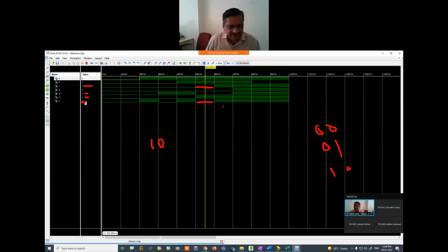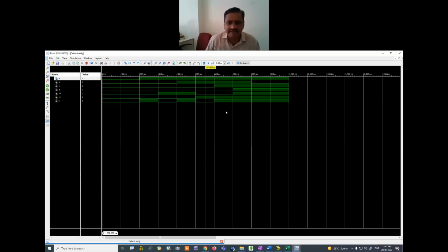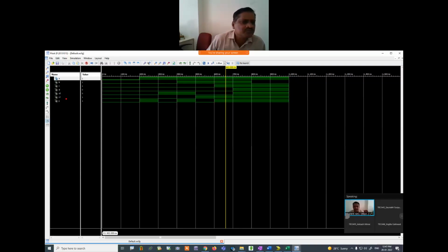If we come to this window, now look at this carefully. In this particular window, what is S0? S0 is 0. What is S1? S1 is 1. Still our select line is 1 0. If the select line is 1 0, our output will be the same as C. Now look at this instant, what is C? C is 1, that's why your output is 1. Now look at this part. This part is C, that's why our output is also 1.